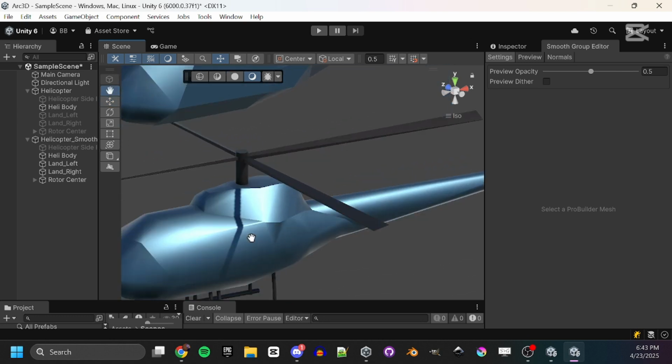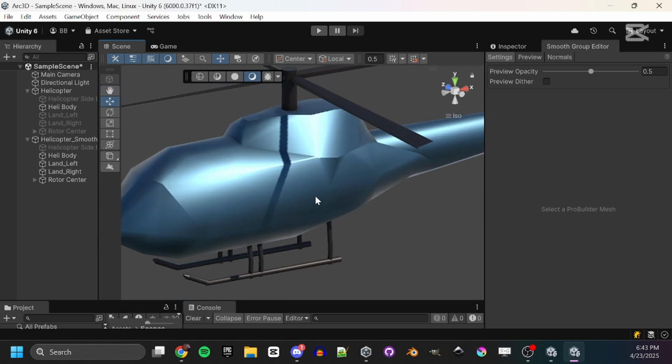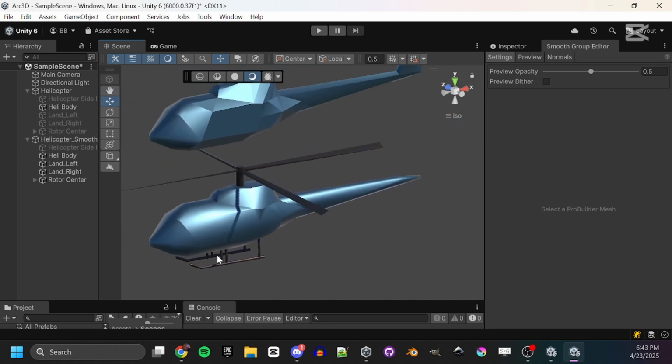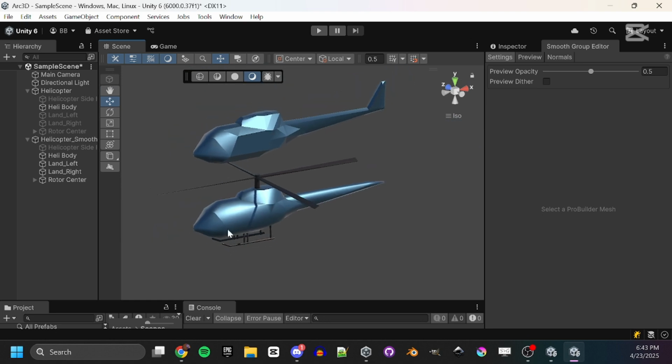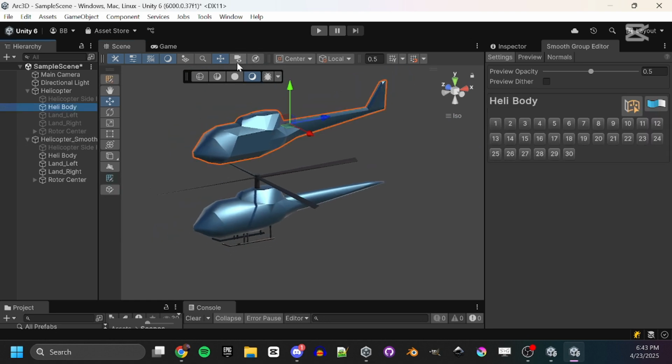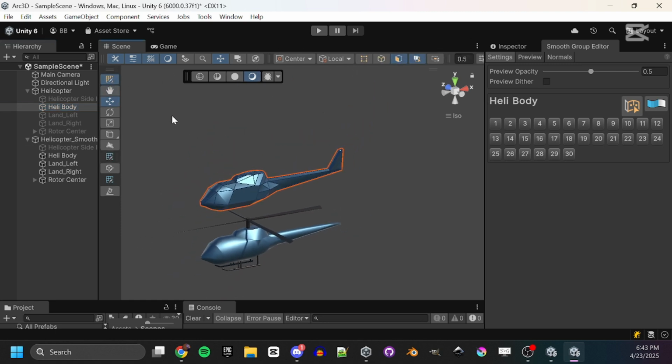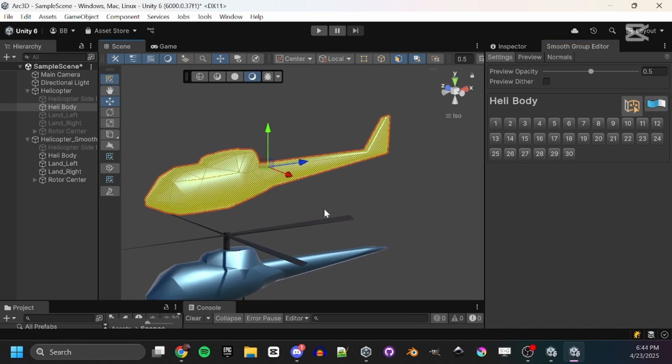So for example, with this helicopter, I made this whole body part of a smoothing group, but this is a separate smoothing group, and so is this. That's how I got this hard edge here and this hard edge here. So smoothing groups, if you want to make a soft organic shape, like a bird or a teddy bear, chances are you'll take your model, go into face select, select all the faces, and then I double check, yeah, I got the backside as well, and make them all part of one smoothing group, then they all get smoothed together.